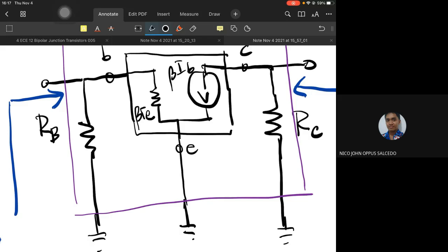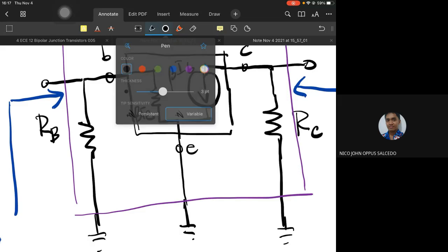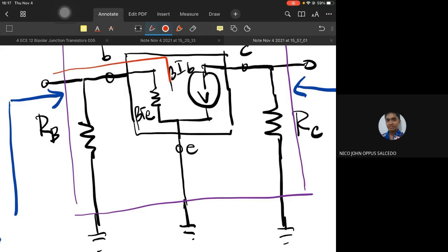So when you say input, it's just the input side only. Okay? Here. Is it obvious which resistances or resistors are involved? How many resistors are involved at the input side? Just one, sir, RB. Actually, there's one more, beta RE. RB, and beta RE at the input side.